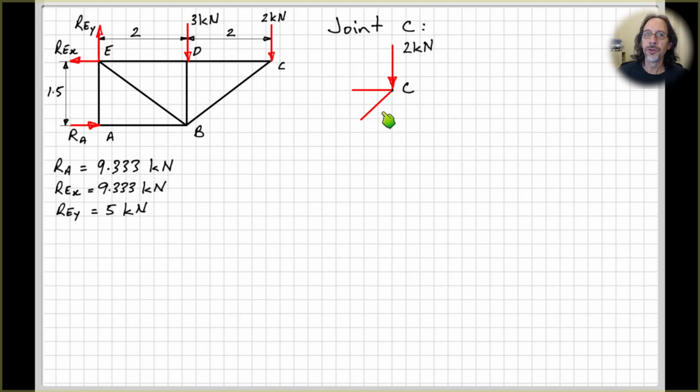And then when you do your free body diagram and write your equations of equilibrium according to the arrowheads on your free body diagram, if the member is in compression, you'll get a negative answer. Don't then go and change your arrowhead on your free body diagram. Just leave it as it is, and note in your answers that the negative number indicates that member is in compression.